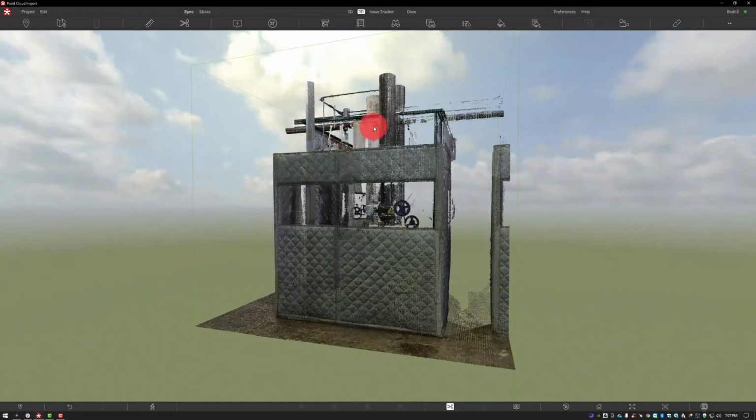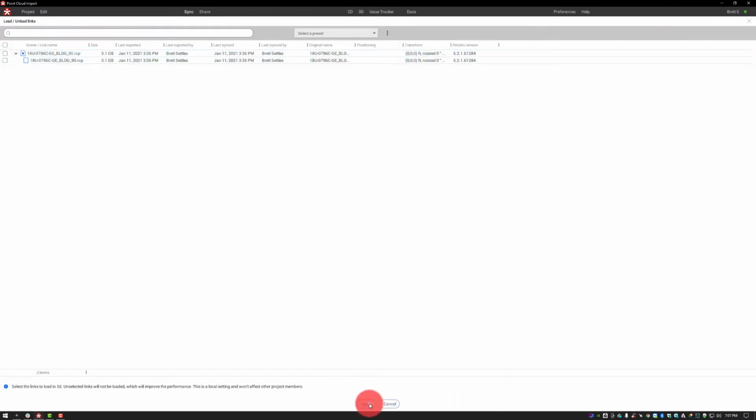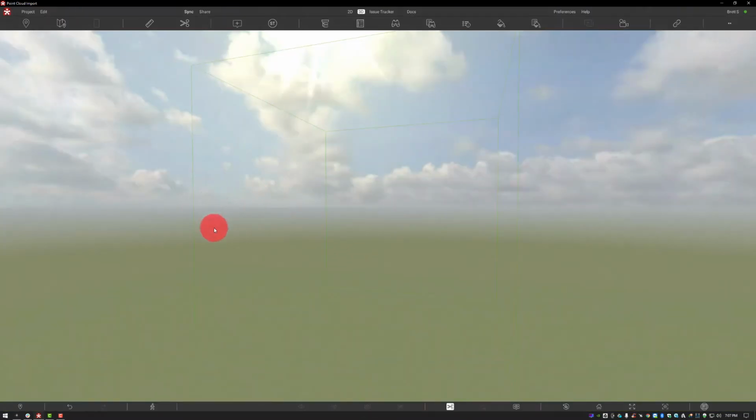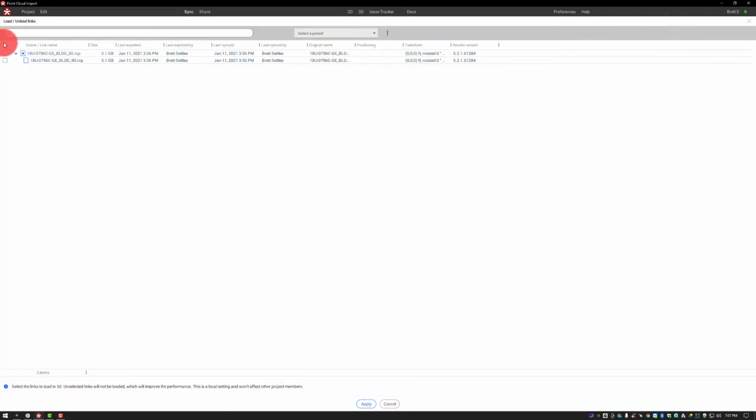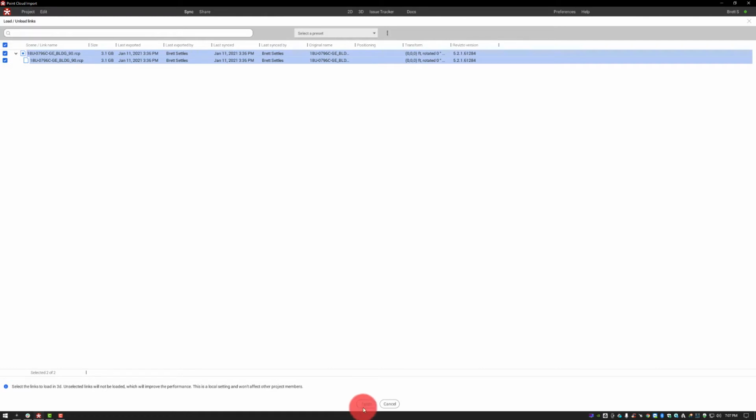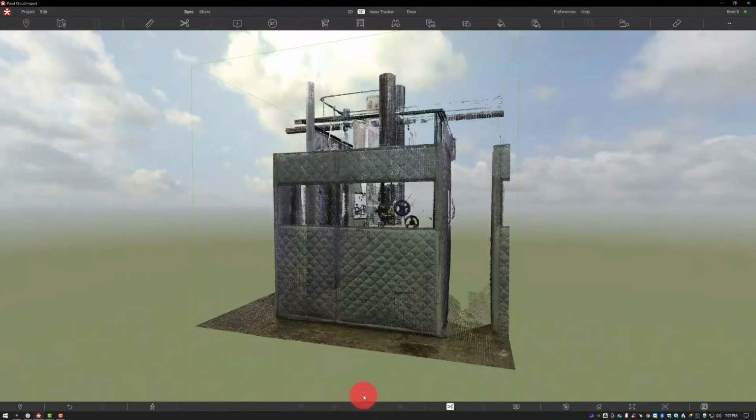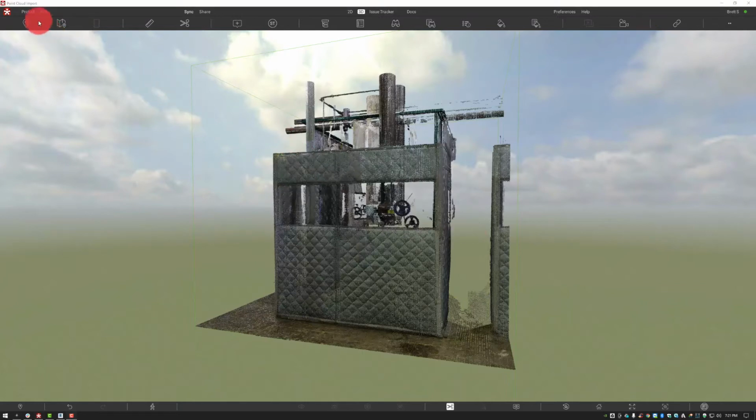Here we can also link and unlink the point clouds. This is really great going back to that RCS workflow because now we can section off a very large point cloud and only show parts of it that are relevant to what we're doing and hide the parts that are not relevant. Very important for field and iPad workflows on lower end devices because those may not have the power to show the entire point cloud, but by loading and unloading these, we can actually visualize a large project in a single environment by toggling on and off the various aspects.